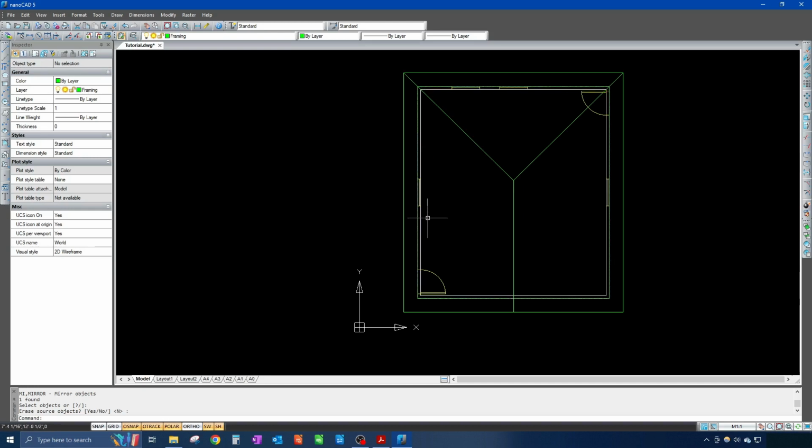Now, in the next segment, we're going to add our rafters. These are the main beams that form our framing. In the United States, these rafters are typically spaced at either 12 inches, 16 inches, or 24 inches, depending on, I think, the city or the local municipality. For now, just to keep it simple, I'm going to keep them at 24 inches.